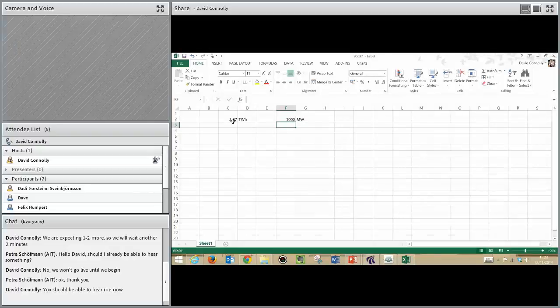If that 1000 megawatts operated for all hours of the year, let's just calculate that. So I'm multiplying 1000 by the number of hours, then I would get approximately 8.7 terawatt hours. So what I've done here is just calculated what the production would be if the wind operated all the time. So if I had 1000 megawatts operating all hours of the year, I would get 8.78 terawatt hours.